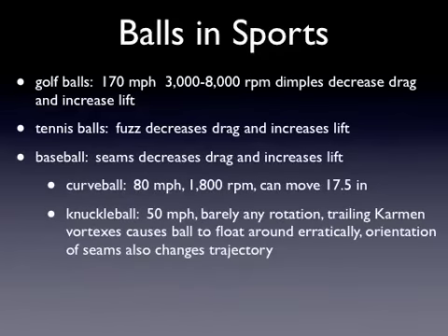Another pitch that's really interesting from a fluid dynamics or fluid mechanics standpoint is the knuckleball. This is thrown deliberately with hardly any rotation. And what happens is you get a really unstable boundary layer. And remember when we talked about those oscillating Kármán vortices? If you remember, we just looked at that in 2 dimensions, but if you think about that in 3 dimensions, you have a vortex forming behind one side of the baseball, and that low pressure zone will cause that ball to move in that direction, and then that'll peel off, and then another one will form somewhere else. The ball will move in that direction, and then another direction.